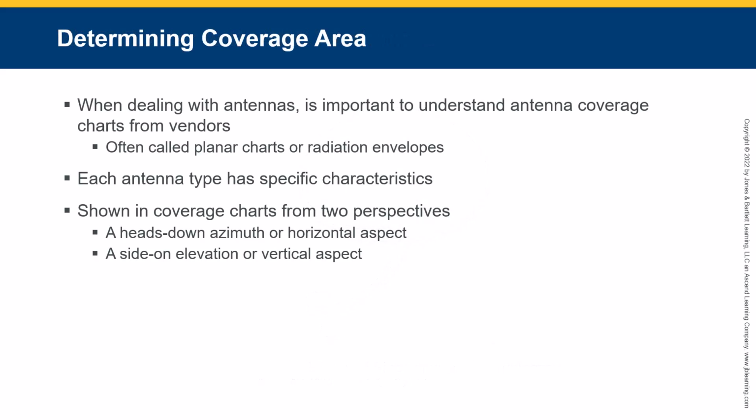So to determine the appropriate coverage range, you need to do a few things. First, look at the antennas. It's important to understand the antenna coverage from the different vendors. So you will have to look at what antenna from a specific vendor you're going to be using to gauge your coverage area. That kind of sounds like a site survey. It really is, and we're going to get into that in just a few slides, but I did want to point out that there are structures for that.